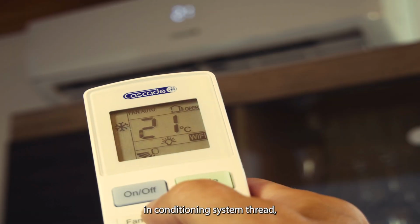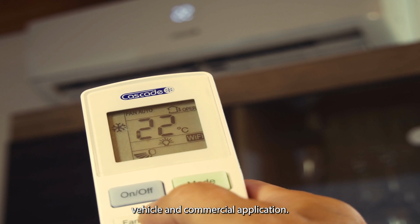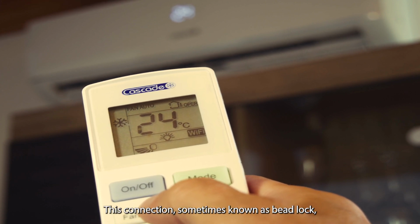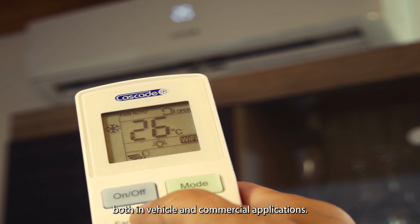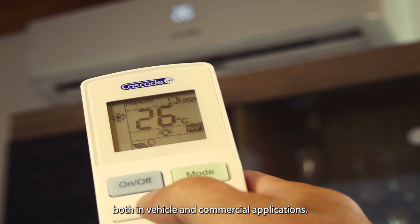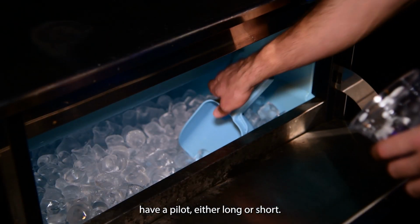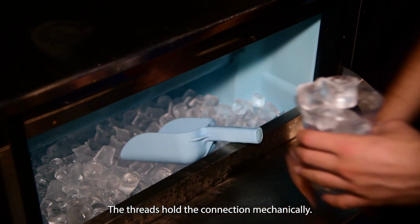The end is a special application in air conditioning system thread. O-ring pilot threads, vehicle and commercial application. This connection, sometimes known as beadlock, is common to air conditioning systems, both in vehicle and commercial applications. Both the male and female halves of the connection have a pilot, either long or short. The seal takes place by compressing an O-ring adjacent to the bead of the tube. The threads hold the connection mechanically.